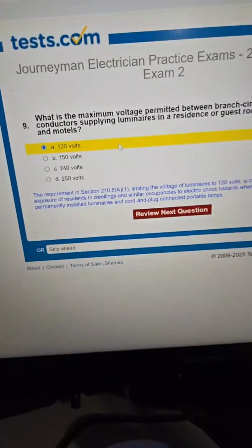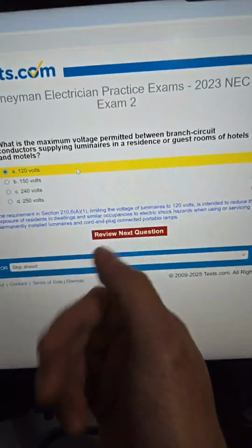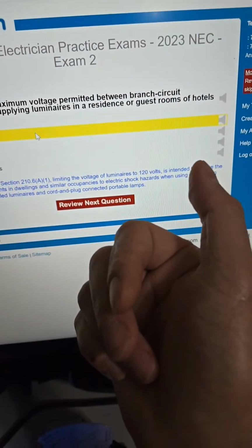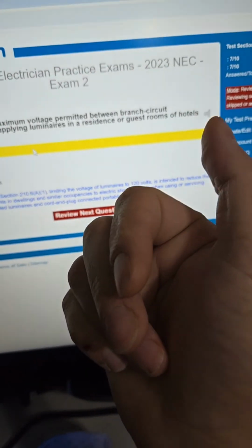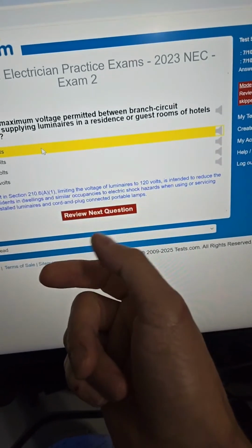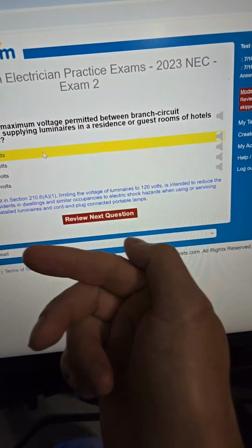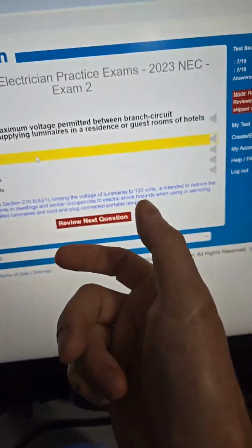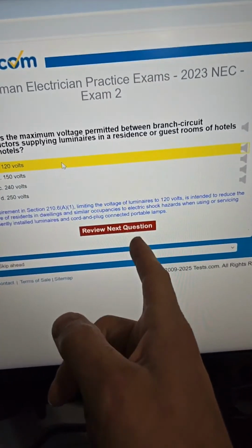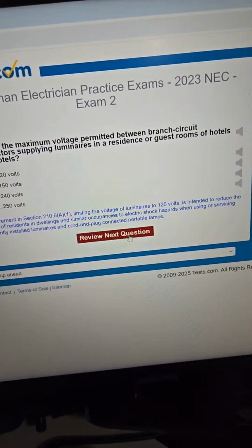If you have a receptacle and part of that receptacle is switched and part of that receptacle is constantly hot, it's your obligation to make sure they go in the same phase. And if you're not an electrician, you're not going to know what I'm talking about. But this is a requirement here. So, yeah, there you go.